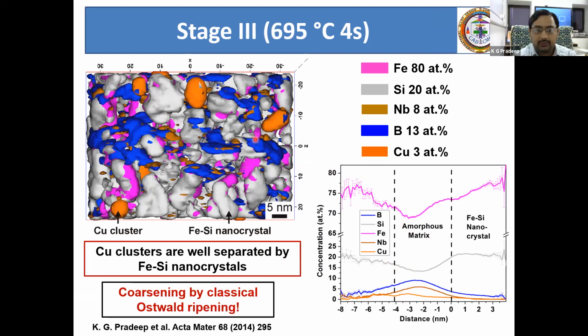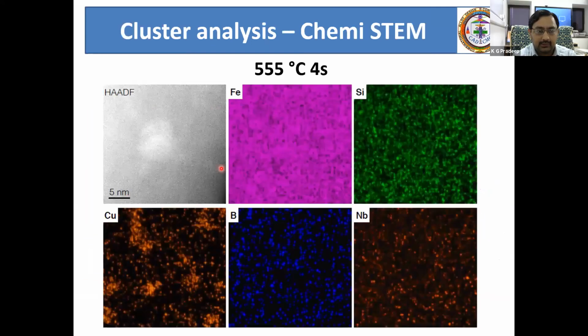Now the same thing, if you try to image with TEM, it is a high resolution aberration corrected microscopy. You can see here, even if you do this ChemiSTEM, which is the latest advanced TEM that we tried, you can now see the copper distribution is quite sporadic. So it's not like an individual cluster in a 3-dimensional form that you are able to identify here.